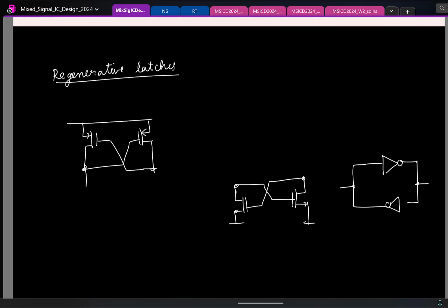That is basically, you put NMOS and PMOS in together, that's the CMOS. So you can have multiple kinds of latches to make a comparator. But at the heart of any regenerative latch, you will find one of these structures. That is again, to get this regenerative action, the e power plus t by tau, you need the small signal negative impedance, and that is what is being emulated by each of these structures.